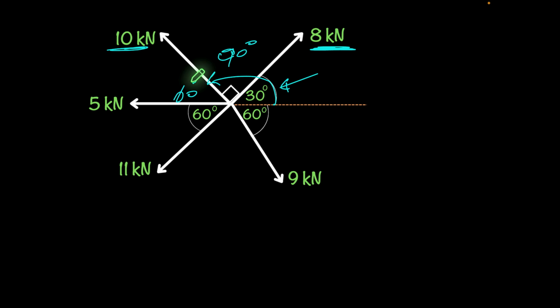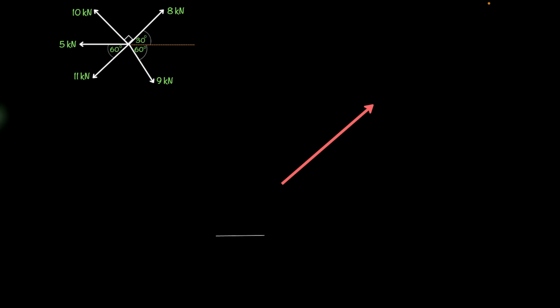Now let's get into how we draw the vector diagram. When you're drawing the vector diagram, your first step is to ensure that you establish a scale. So just make a note that your step one is to ensure that you establish a scale. Now, if you're using some form of CAD software, then you don't necessarily need to establish any scale. You can just use the software to do that. But if you're using, say, your ruler and your protractor, and you're just using the regular centimeter grid paper, then you will need a scale for your diagram to fit onto.